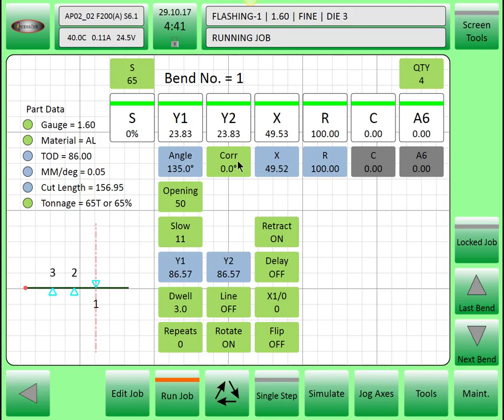into auto run mode. Typical errors such as emergency stop or axis over travel limits or incorrect data are always flagged in red, with the axis or axes that are being affected inhibited.